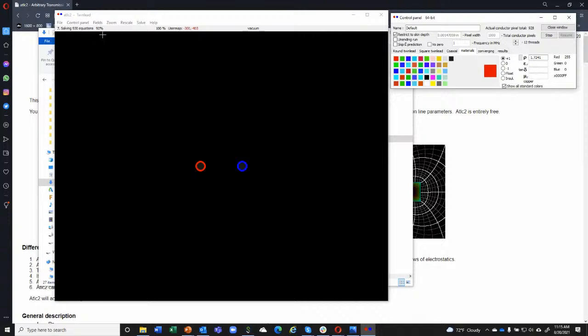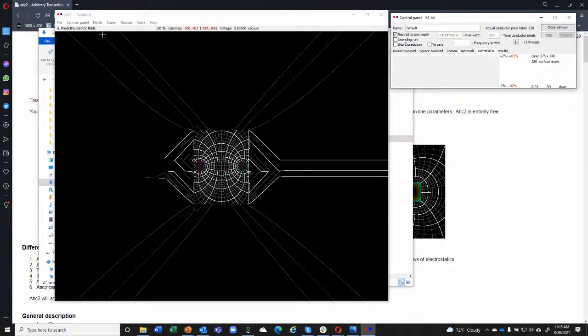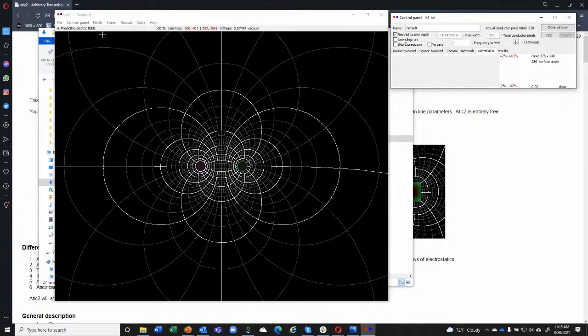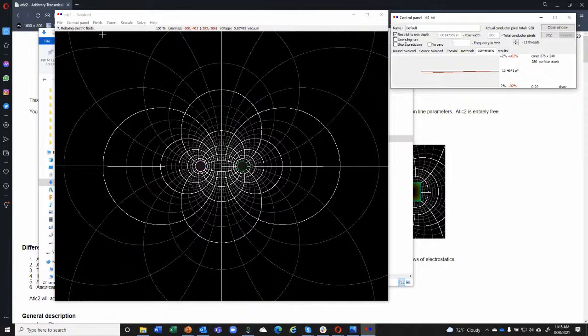So the piece that I'm currently missing here, and this is probably something someone's actually done with Eagle and Fusion, you can run ULP scripts, right? And the ULP scripts. So I have my layer stack design in my PCB editor, and I want to define a trace cross-section for a microstrip or strip line, and then take a section of that and have it generate a bitmap in the correct color scheme to open it in ATLC2.